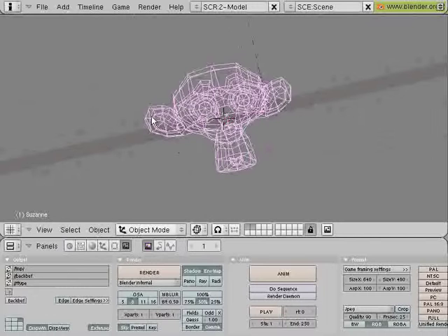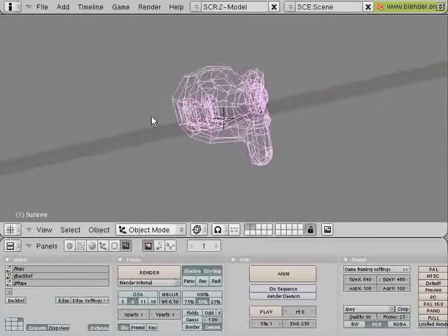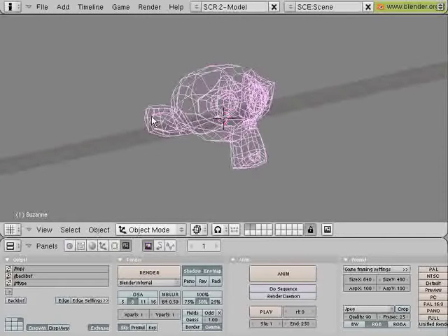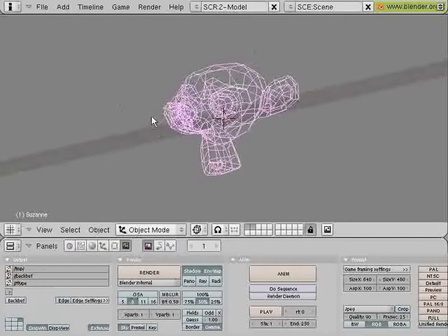Okay. And also you can rotate the view by using what I like to call the directionals on the numeric keypad. If you have a keyboard that has arrows drawn on it, that will help. So if you use the 4, 8, 6, and 2 buttons on the keypad, you'll notice that you can now rotate the view with discrete increments.